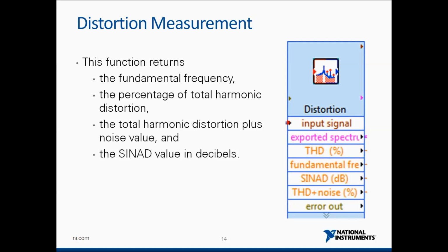So harmonics are basically multiples of the fundamental frequency. In the example that I gave, if I have a square wave of 100 Hertz, I'll have harmonics of frequency 2f, that is 200, 300 Hertz, 400, and so on. Accordingly they're named as first, second harmonic, third harmonic, and so on.